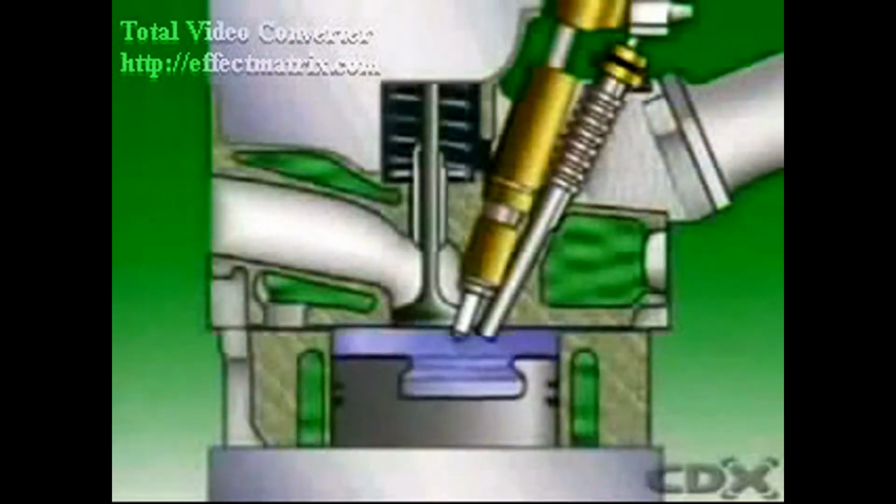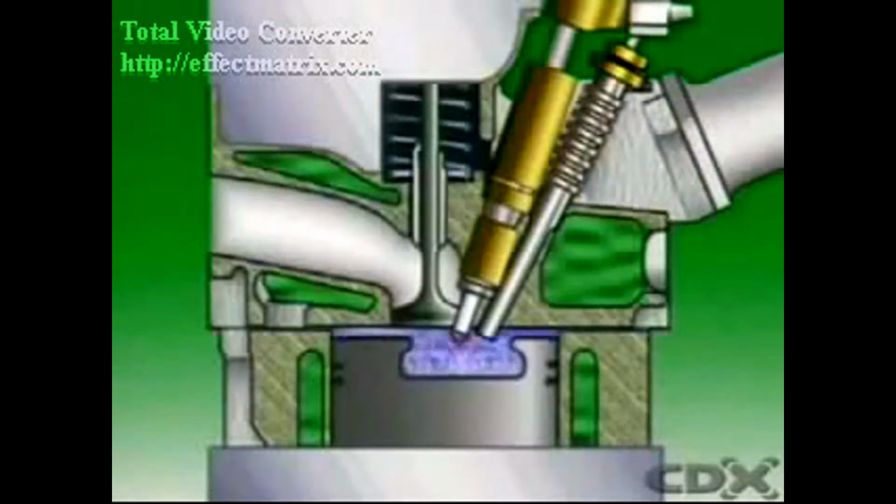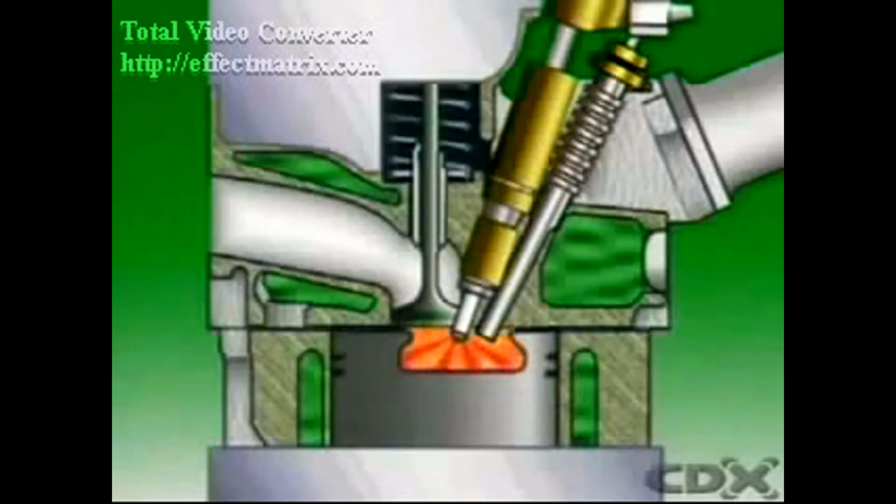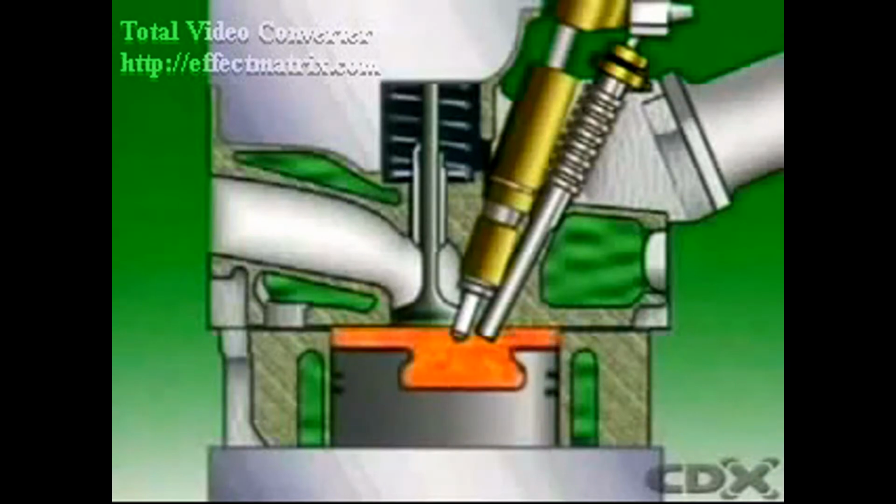They can be single-hole or multi-hole, and they operate at very high pressures, up to 200 atmospheres. They give a hard spray which is necessary to penetrate the highly compressed air. The fuel has a high velocity and good atomization, which is desirable in open combustion chamber engines.